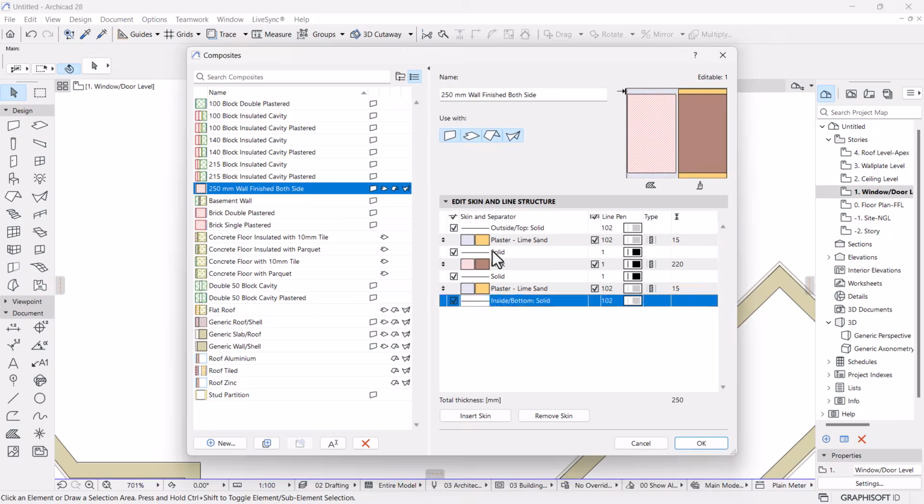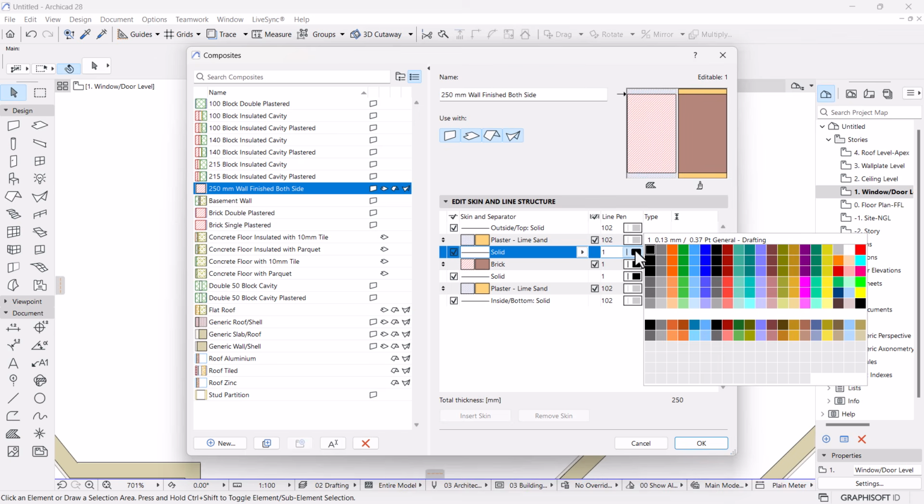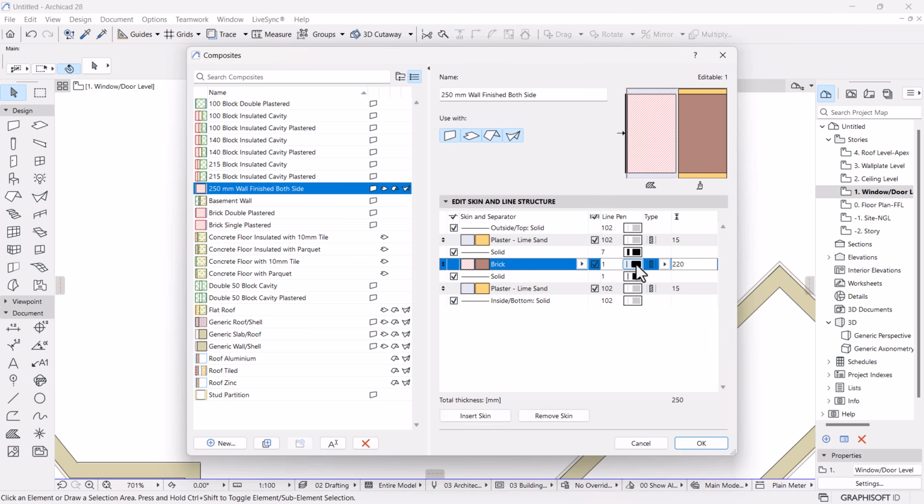And then for the brickwork, because I want them to be thick, I'm going to use a wall line for both this, like that. It's going to be pen 7 for all. You can even see the difference between this. In ArchiCAD, this is how the weight of the line or the pen is being represented.